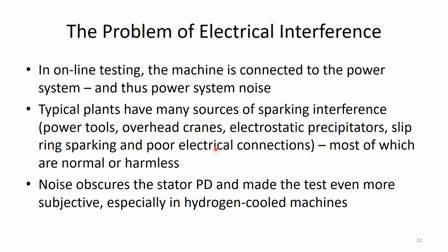And if you're measuring those, because you're connected to the power system and your capacitor is measuring those signals at the same time, it's also looking at the stator PD. And quite often, especially in the larger gas turbine plants, combined cycle plants, coal-fired and nuclear plants, that noise can be so high, that electrical interference can be so high, that it really washes out the stator PD, and you need a really good expert to separate the PD from the noise. And of course, the original test service providers from the OEMs back in the 50s and 60s and 70s, and even now, had those kinds of experts.